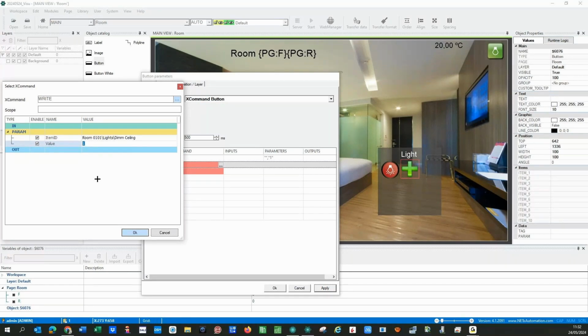In binary, if you want to dim up 100%, because you will stop, you will break this dimming with the long release, long down, as it mentions there. This is the third option I will configure later on. But if you press down, you will need the following information to send in 4-bit. In 4-bit, in binary, should be 1 to go up, 001 for 100%. So up 100% of the light. This is to dim up the light.